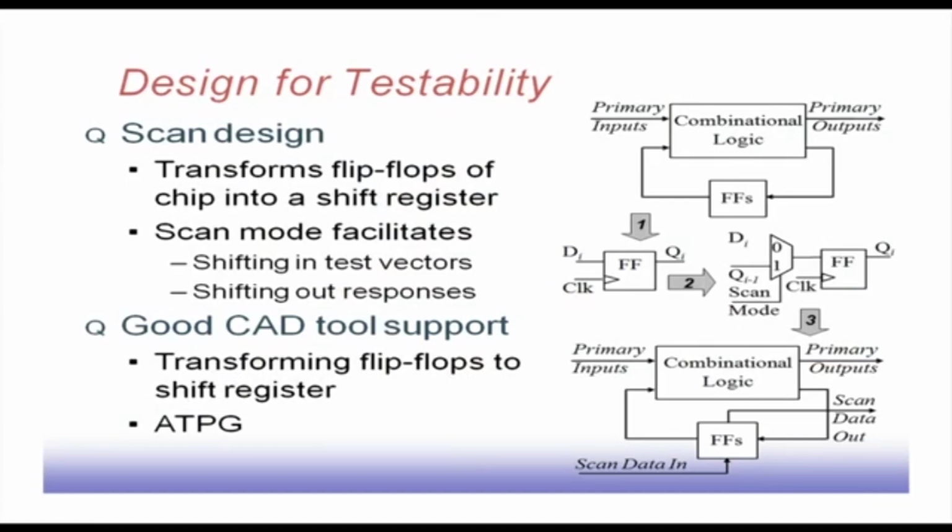This is one of the very standard designs. The flip flops that we have in the circuit are converted into scan flip flops, and they are connected in a shift register organization, and whatever value we want to have in those flip flops, we can shift them serially into those flip flops, and accordingly we can apply some desired test pattern there. The CAD tools that we have have a facility by which we can transform all the flip flops into this shift register. That can be done, and these ATPG tools are also there, which take help of these scan based circuits, so that the test pattern generation becomes simple compared to a sequential circuit.